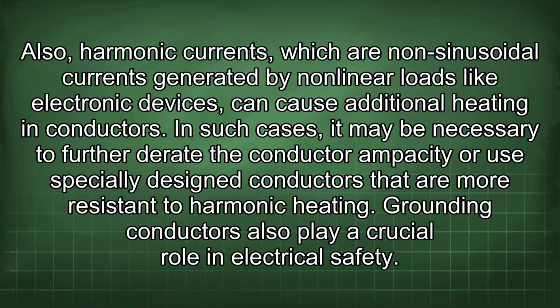Also, harmonic currents, which are non-sinusoidal currents generated by nonlinear loads like electronic devices, can cause additional heating in conductors. In such cases, it may be necessary to further derate the conductor ampacity or use specially designed conductors that are more resistant to harmonic heating.